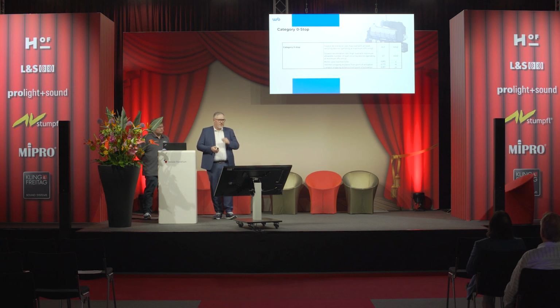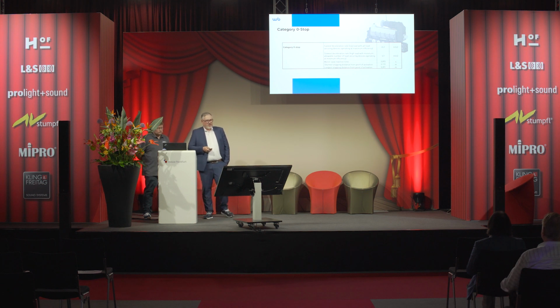The reaction time that you see here in this case is not taking into consideration any processing in the control system anymore. It's really the time it takes for the rectifier to unload, for the contactor to close, and for the brake coil to close the brake actually. The resulting stopping distances would then be something between 18 centimeters and 40 centimeters roughly.